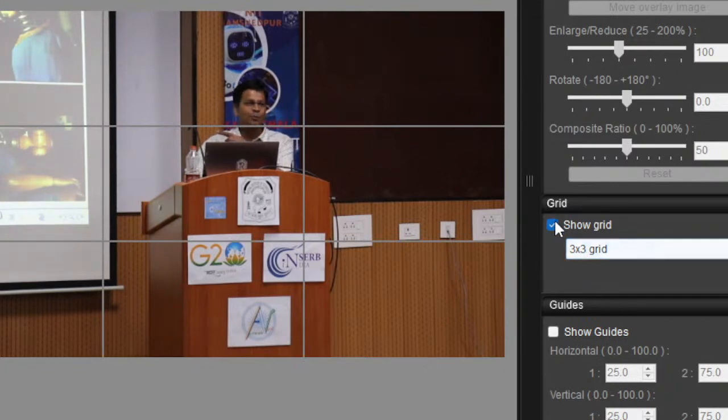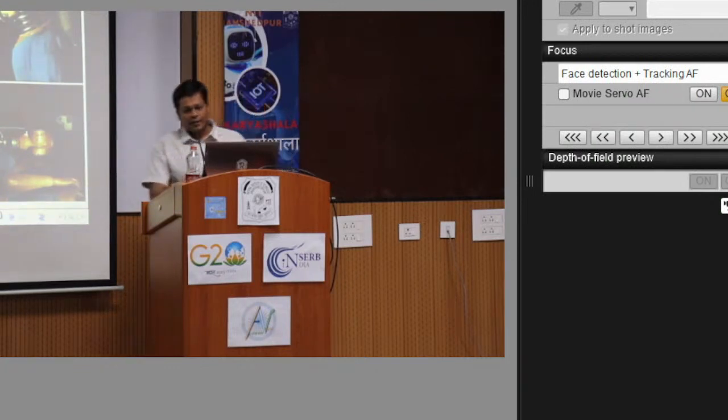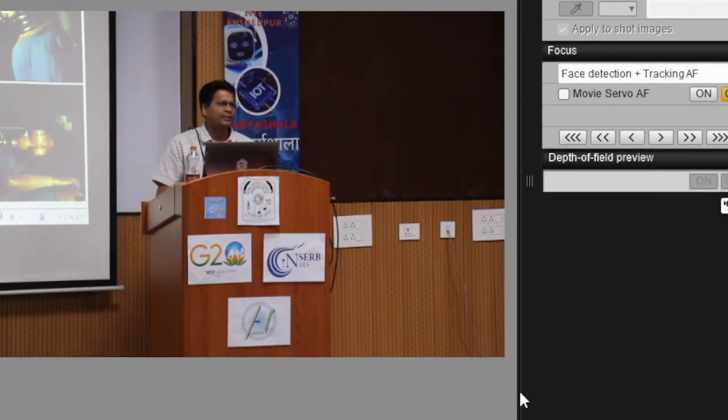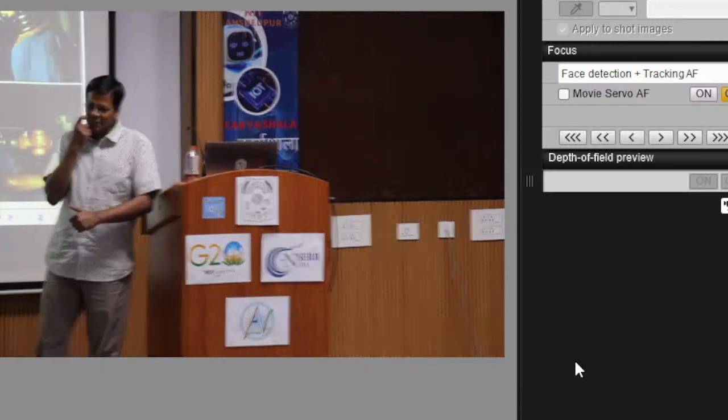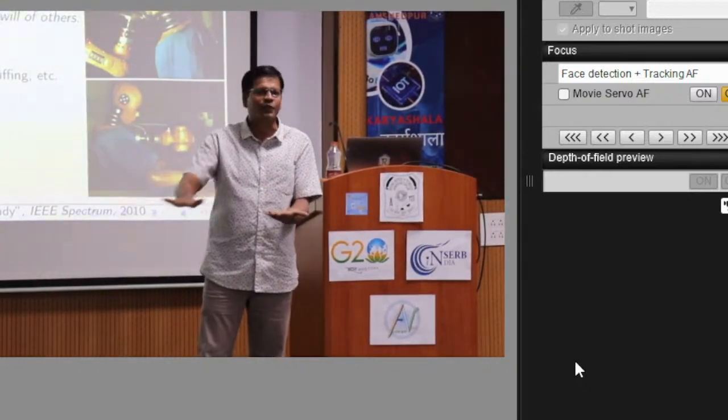And mind it, this is a cobot, this is not even a robot. And you will understand most of it. So that is what robotics is. Okay, so assembly task, surface finishing task. Again, surface finishing tasks like grinding, polishing, buffing, deburring, whatever this kind of task. What does it do? Basically, you have to maintain a constant force against your surface.